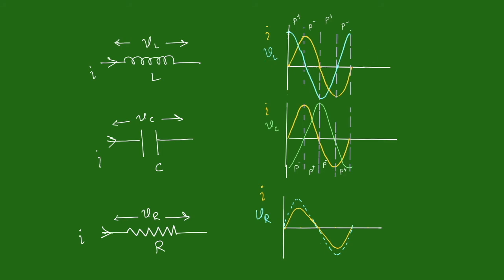And hence, you can notice from these two graphs that the product of current and voltage for the inductor as well as for the capacitor is not always positive through one complete AC cycle. For the first 1/4 it is positive, for the second 1/4 it is negative, for the third 1/4 again it becomes positive, and the fourth 1/4 it becomes negative. In the same way, for the capacitor also it is changing for every 1/4 of the input cycle, and hence over